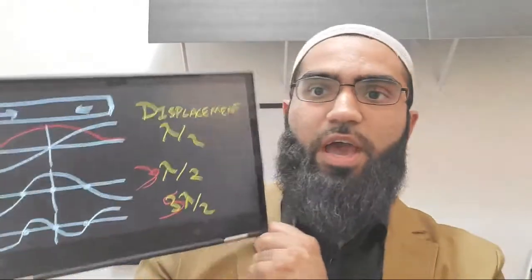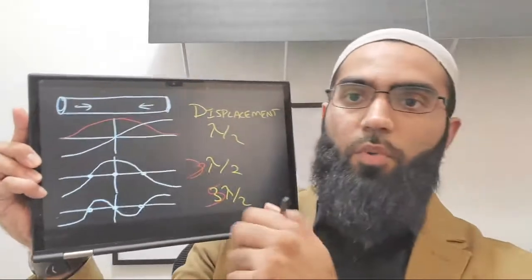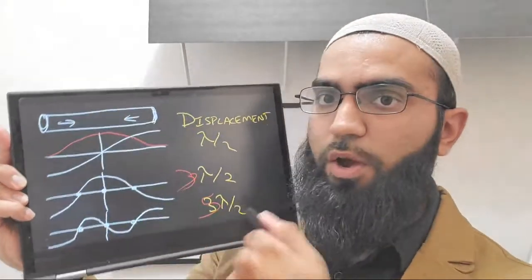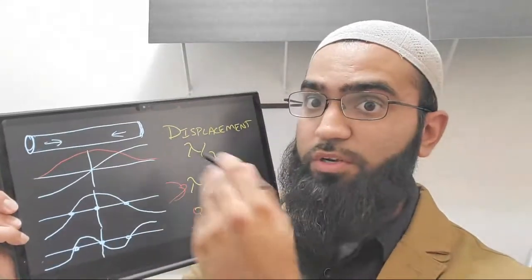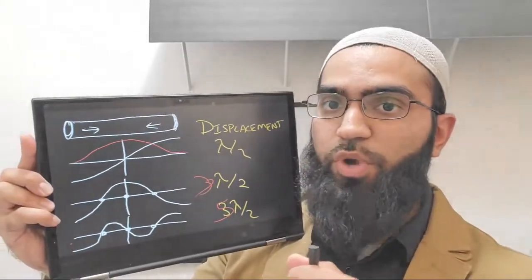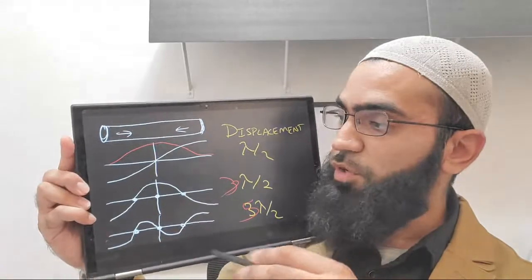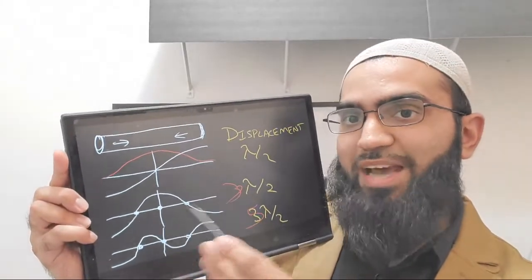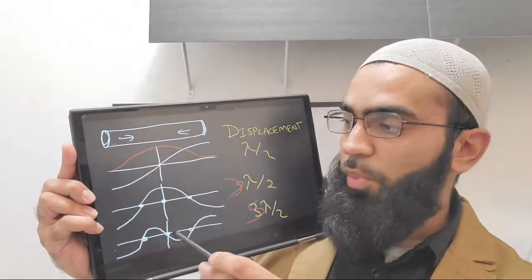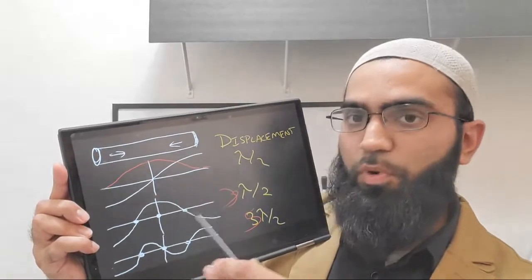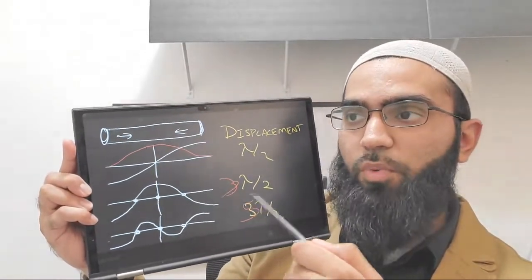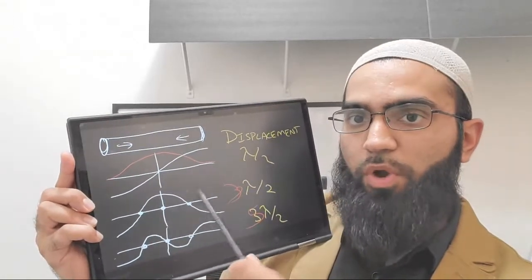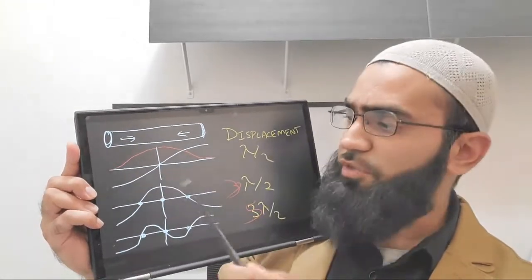So as we keep increasing the mode number, we also have a different number of wavelengths in the material. These will also be higher frequencies, right, according to these ratios as well. So these ratios and wavelengths, depending on the frequency you apply, you will excite certain wavelengths within the material. So it's important to know your wavelength, to describe what frequency, where your nodes are going to be, where you want to put your piezos and attach your other components.